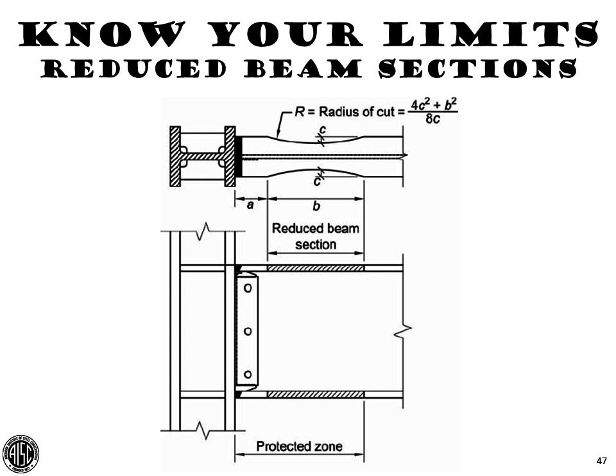Then again, this is just an example. I'm picking a reduced beam section to highlight the fact that each of the connection types in AISC 358 have pre-qualification limits associated with them. Sometimes what we see is an engineer will choose columns and beams and then sometimes they'll designate a connection type that may be included in 358, or sometimes they'll leave it completely up to the decision of the fabricator. But then it turns out there are no pre-qualified connections that will meet the requirements.